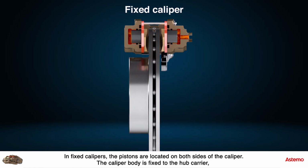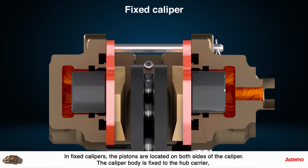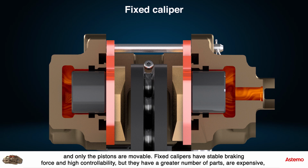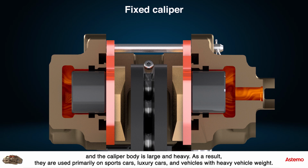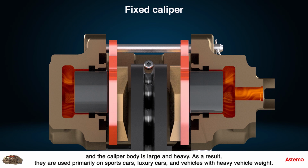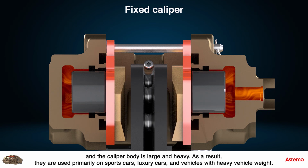In fixed calipers, the pistons are located on both sides of the caliper. The caliper body is fixed to the hub carrier, and only the pistons are movable. Fixed calipers have stable braking force and high controllability, but they have a greater number of parts, are expensive, and the caliper body is large and heavy. As a result, they are used primarily on sports cars, luxury cars, and vehicles with heavy vehicle weight.